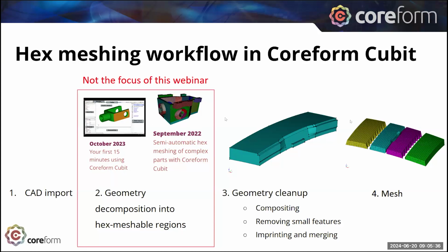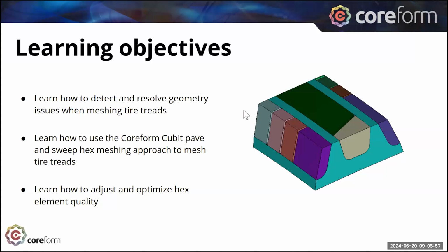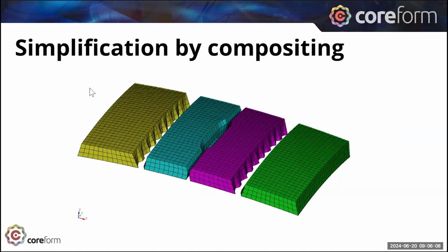I'm going to actually spend most of my time doing some live demos showing some geometry cleanup and meshing on a couple of fairly simple tire treads. Now, I'm going to grant you up front within the webinar, these are simple, but they show some techniques that I wanted to demonstrate. So I think we've learned how to resolve the geometry, use the pave and sweep, and we'll just use some geometry techniques to help control our mesh.